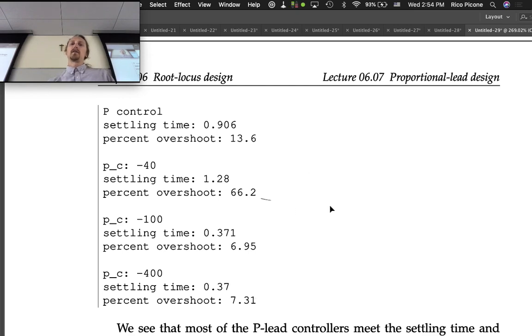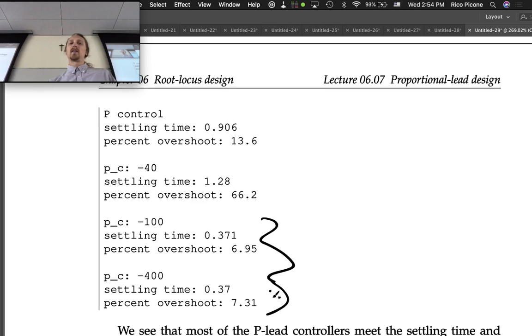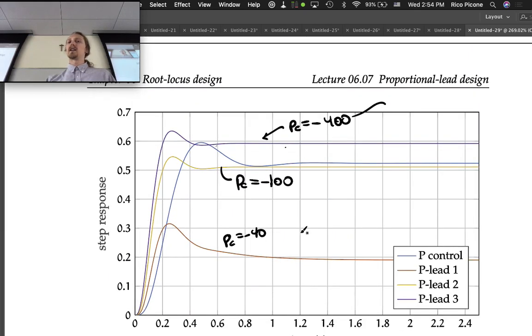In terms of steady state error, really none of them is going to give us all the steady state error improvement we need. We're going to need a lag compensator. But the negative 400 location was best for that. So I would probably go with the negative 400 location. Now, there are some other considerations that would be more downstream than this.